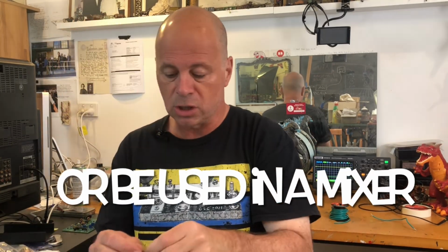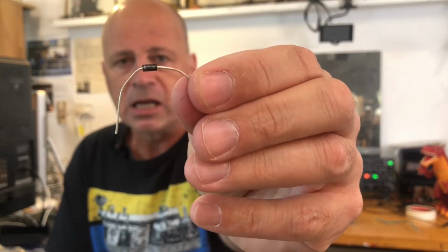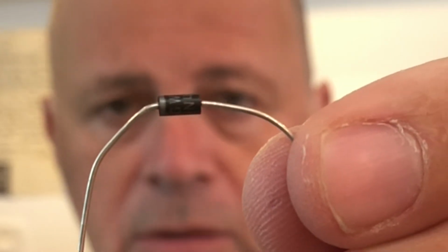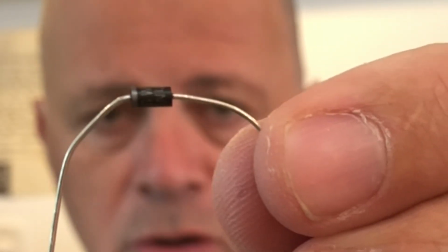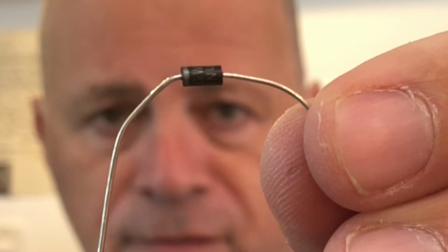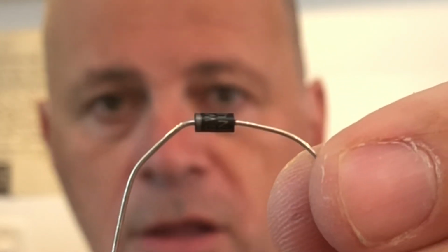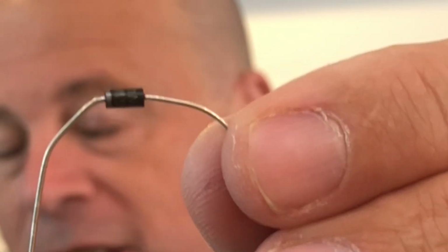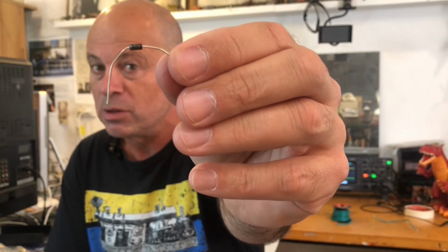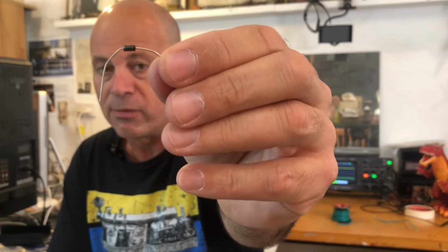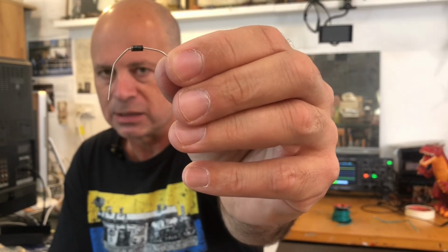And of course, the diode we're going to be looking at today, a power diode. It's a 1N4004. And you'll probably notice that the thing that these diodes have in common usually also is that if they have a body, they'll have a stripe. And the stripe is telling you that that is the negative side. So the other side has to be the positive side. So it's a way of making sure that you put this in the correct way around if you want it to conduct. Enough of me babbling on here.